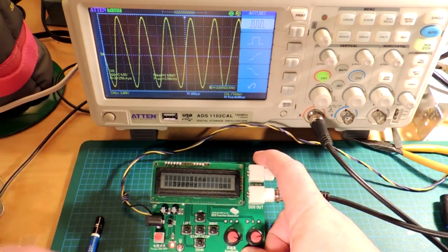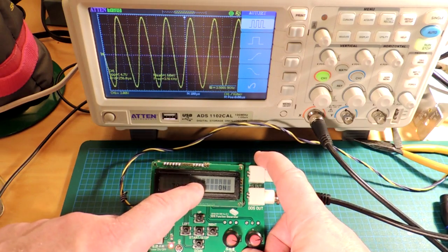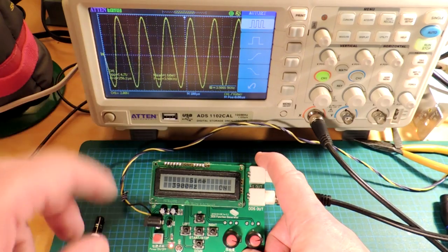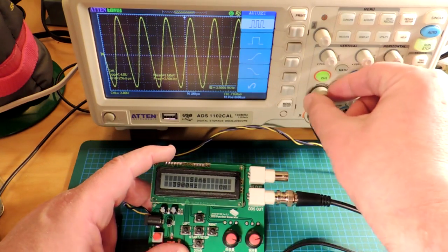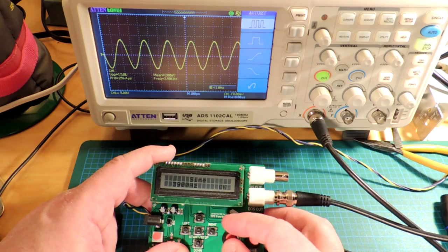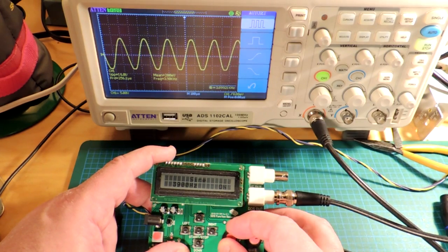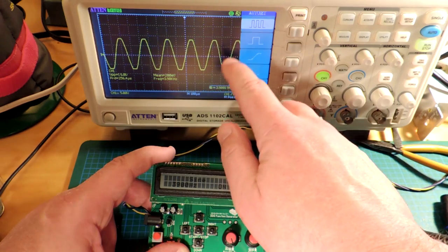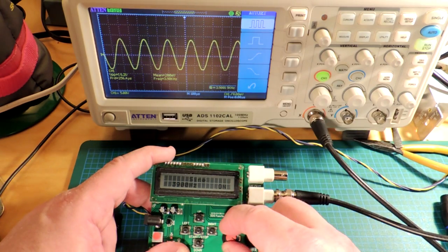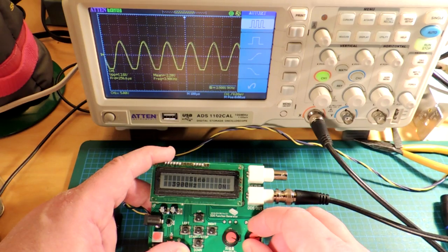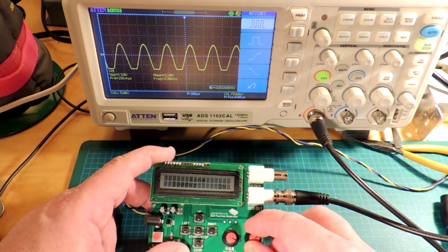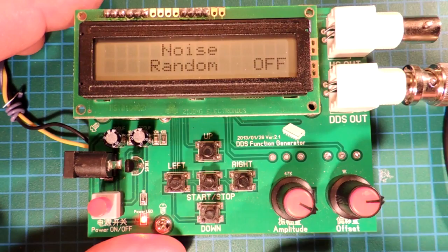Okay, powered on. Obviously my oscilloscope is showing a waveform. It's in the sine mode, and it's producing a 3,900 hertz frequency. Very typical for, say, audio work, if you're trying to trace an amplifier and trying to inject a signal into it. The amplitude adjust, of course, adjusts the size of the waveform. You can see it clips as it gets to the edge of its excursion range, and there's an offset as well. You can see this behavior where it will clip, of course, and that's fine.